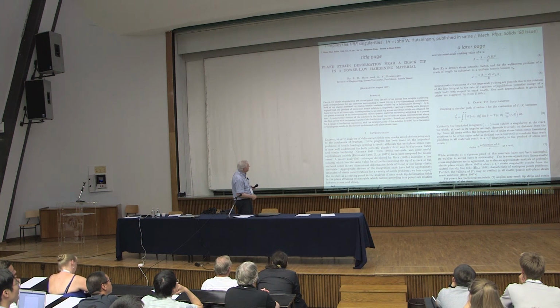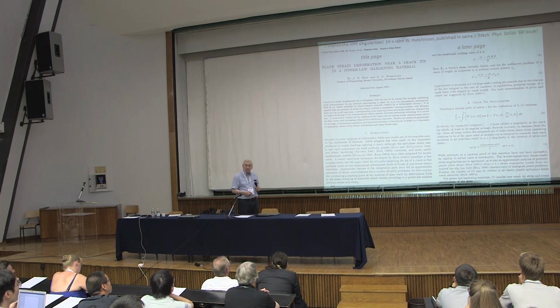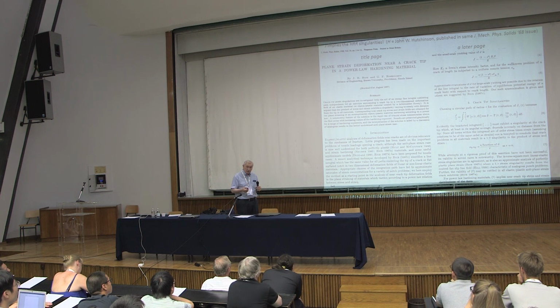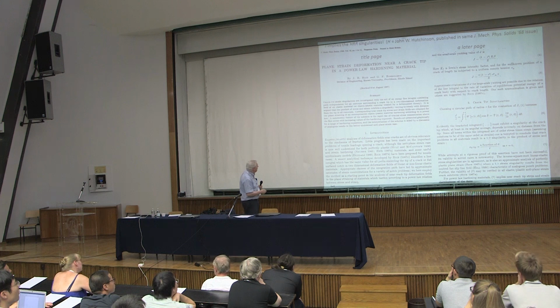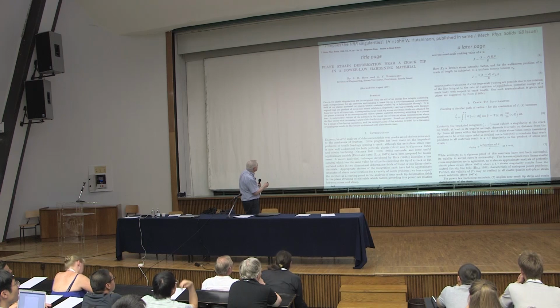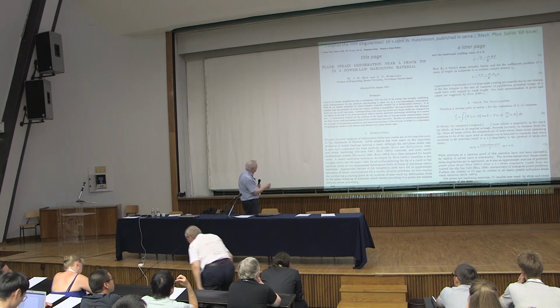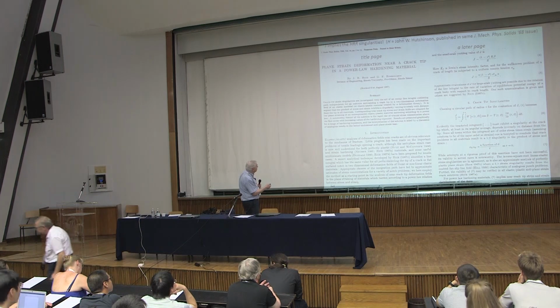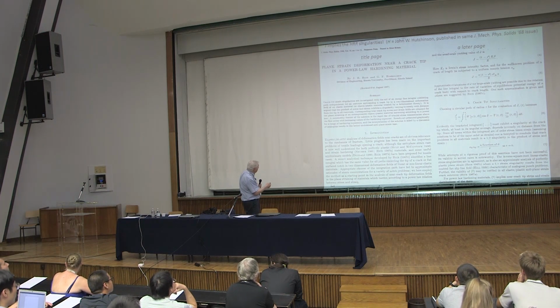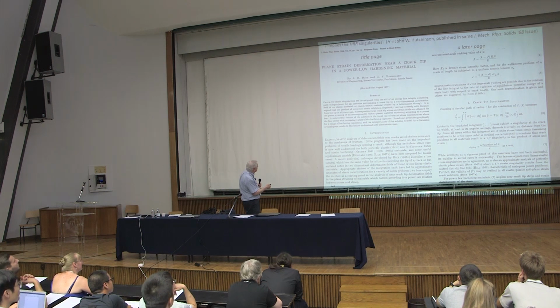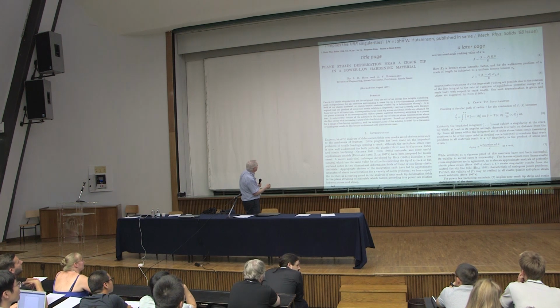And then an immediate application of this was to working out the form of singularities at crack tips in nonlinear materials. So the easiest one to deal with is one where, at large strain in the plastic range, stress went as strain to some power, so-called power law hardening. And this is work I did with Joran Rosengren, who unfortunately passed away early, but he was a PhD student from Sweden who was working with me in that era.